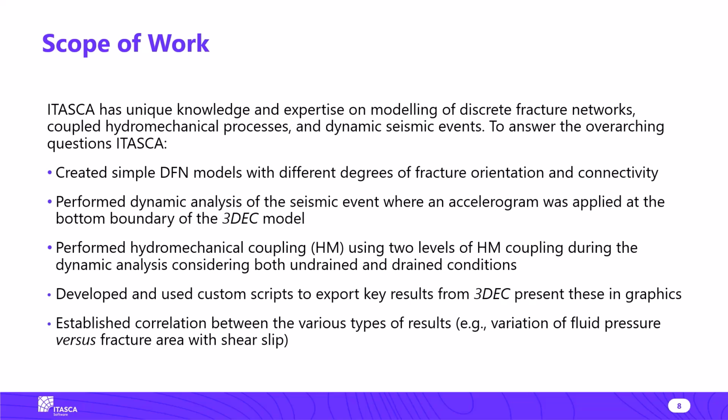Under drained conditions, fluid flow is active and coupled with rock mechanical effects. So in this degree of hydromechanical coupling, fluid pressure diffusion is considered. Under undrained conditions, there is no fluid flow. The deformation is not induced by diffusion-related fluid pressure changes, but by mechanical loading occurring on relatively short time scale, so the fluid pressure diffusion can be neglected. ITASCA developed and used custom scripts to export key results from 3DEC and present these in graphics, and also establish correlation between the various types of results, for example, variation of fluid pressure versus fracture area with new shear slip.